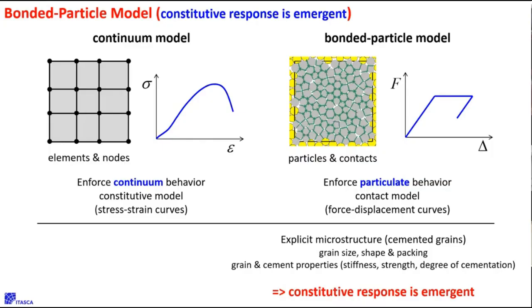Think of a big hunk of rock. If there's no joints in it and it's intact, it'll have a 200 MPa UCS. If you put a whole bunch of joints in it, it's going to be a lot weaker. And at the rock mass scale, it's going to have stuff like that in it. And the way of dealing with this, you could refer to this as a size effect as you go from lab scale to rock mass scale, is an open issue. It's an open research issue.